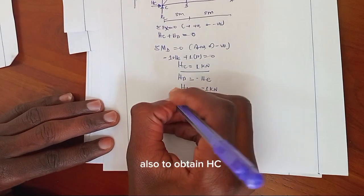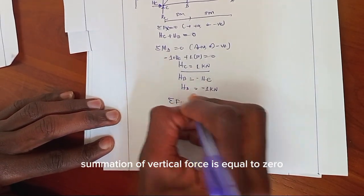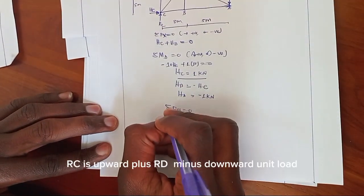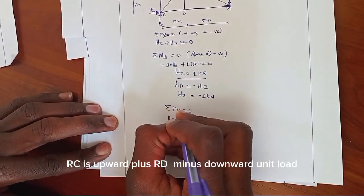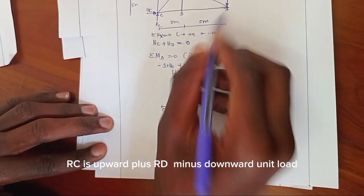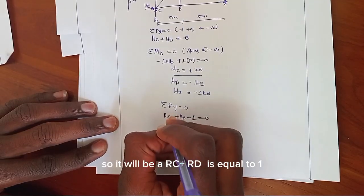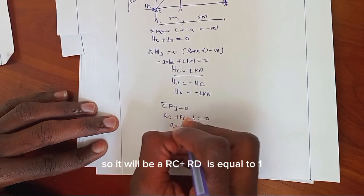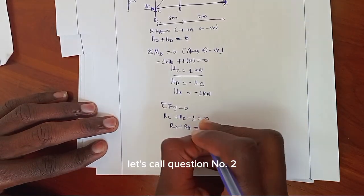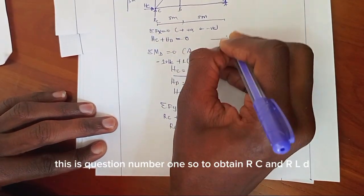Also, to obtain LC, summation of vertical force is equal to 0. Vertical forces we have LC which is upward plus LD minus the downward unit load which is 1 is equal to 0. So it will be LC plus LD is equal to 1. Let's call this equation number 2. This is equation number 1.